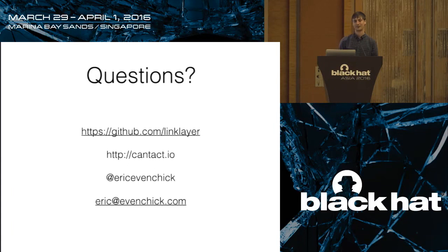That's one example, but other ones include, if I have a diagnostic tool and it has this really cool routine like apply brakes, which a lot of them do for the purpose of bleeding brakes, I can pretend to be the car and say, okay, when I get a request for that routine, I'm just going to send back, yeah, okay, I'm happy, I'll run the routine. Then you just take your diagnostic tool and you start punching all the buttons on it, and it comes up with what every routine code is. That's proprietary information that typically you wouldn't be able to get from a manufacturer unless you pay them the $50,000 royalty for most of them that they're asking. You can really quickly write a script. It's like 10 lines of JavaScript or something to do that type of thing.